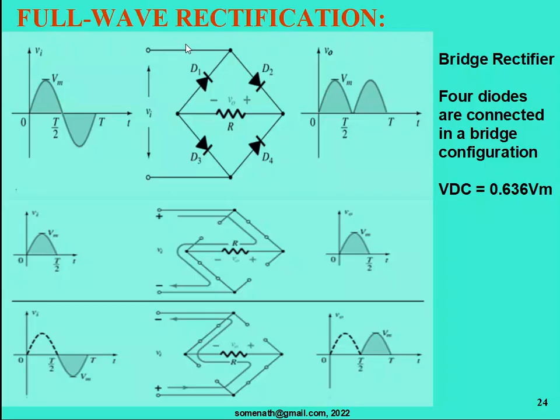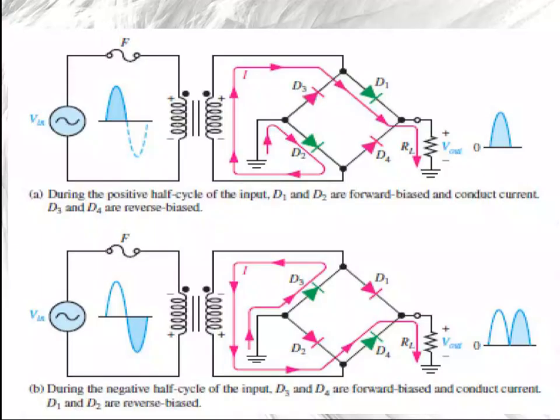So I think it is clear for you why we use the 4 diodes in the bridge rectifier: because we can use any transformer. We don't need the center tap transformer. So that's why we are concentrating on that. The similar representation is shown here with a color image and color arrows, so the lines indicate how the current flows, the same thing I told you, right?